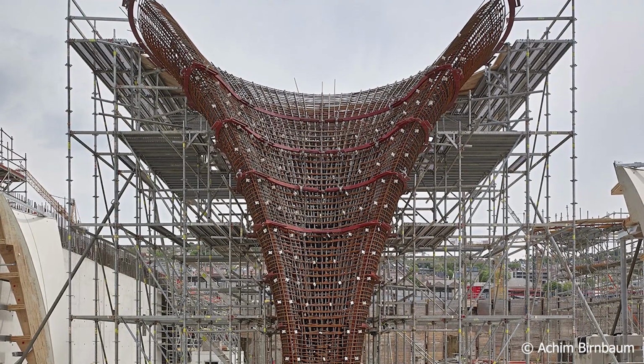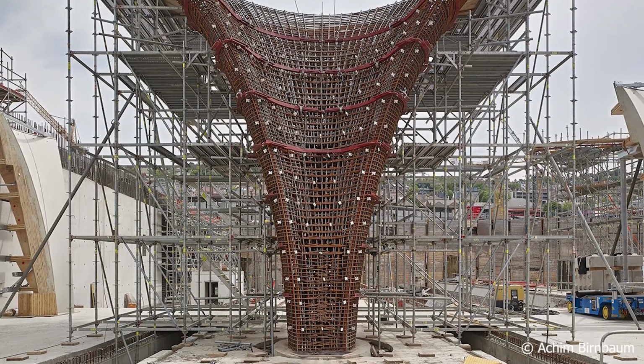So in the end, these 28 tulip columns, they are all different. They are only individual. Any of these individual columns has 11,000 individual rebars integrated. So in the end, a project like this can possibly not be done by hand. From Allplan, you can do the design, you can do the rebar design, but you can directly control the automated machine as well. And then, of course, the question is, what do you do with these 11,000 or possibly 200 or 300,000 individual rebar positions?